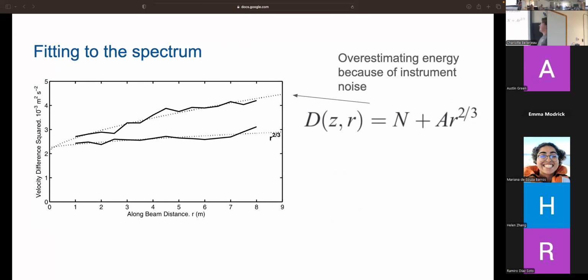So that distance R in our structure function is dependent on the actual size of the features that we're expecting to see. Ideally you want to tune your bin size to be roughly the same distance R as what you're trying to see. So again, for a really low frequency ADCP, you're not going to get anything super useful, but for a pulse coherent ADCP that's higher frequency, that can actually get that lower end value.